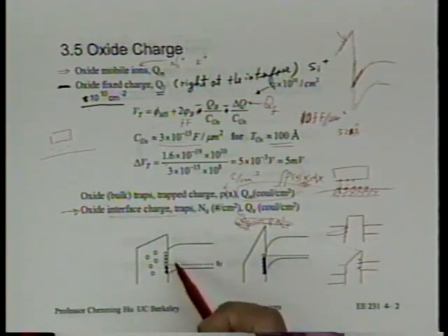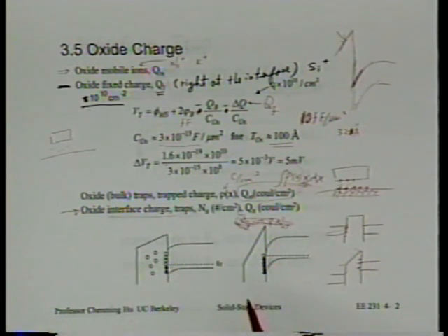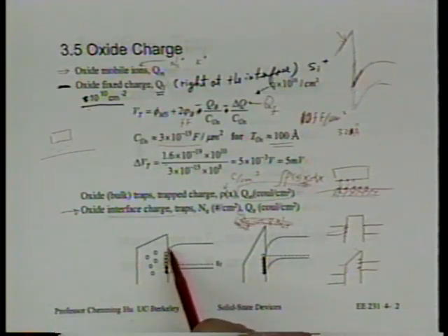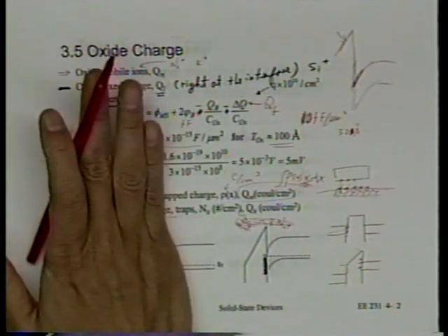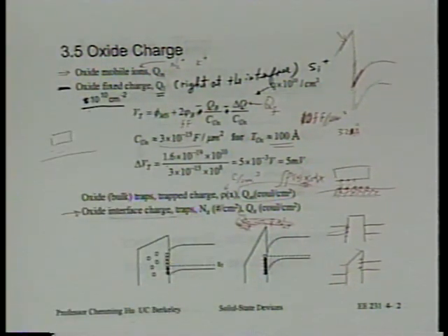That is, in the band gap, indeed, there's not supposed to be states. But that statement is only true in the bulk of the silicon crystal. At the interface, there's no reason that there cannot be interface states. The amazing thing is that with the SiO2 and silicon interface, there are so few interface states.